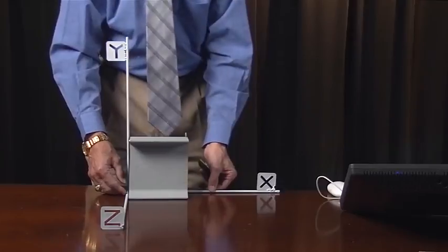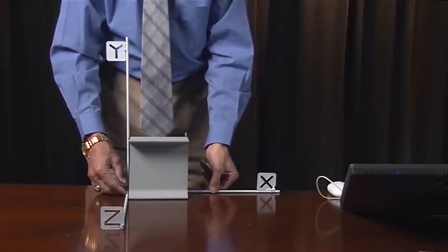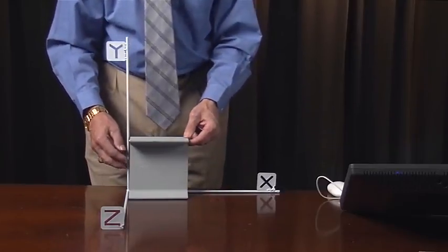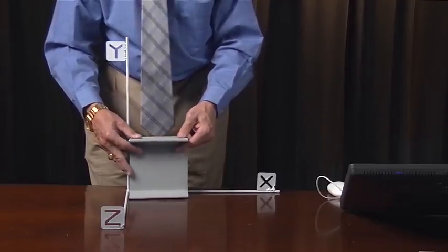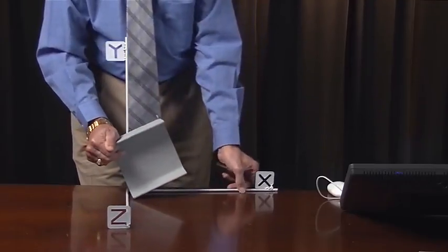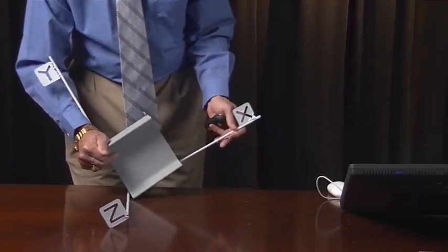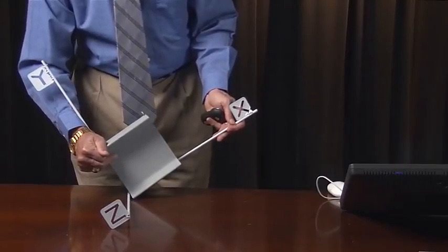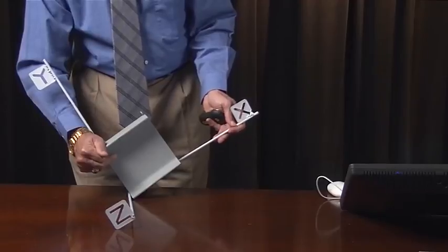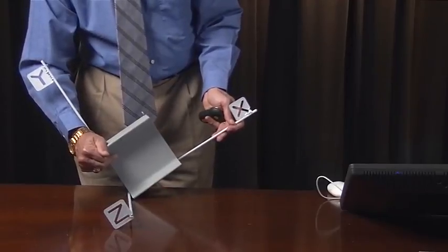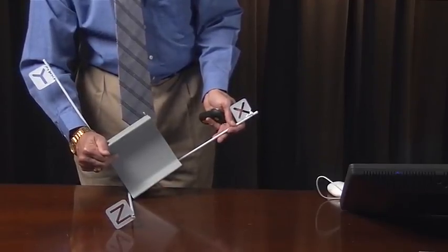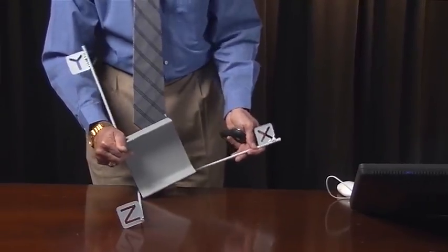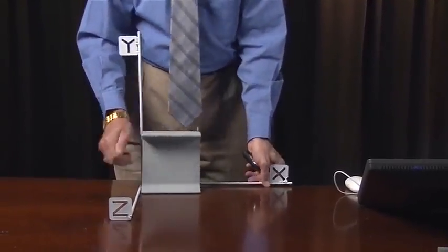Also, on the sum of my forces in the x and the y direction, it has to be two orthogonal directions. So if I had a body on a slope, for instance, and let's say that the x axis was parallel to the slope and my y-axis was perpendicular to the slope, I could also use the sum of the forces in the parallel and the perpendicular direction equal to 0 and the sum of the moments equal to 0 to enforce static equilibrium.